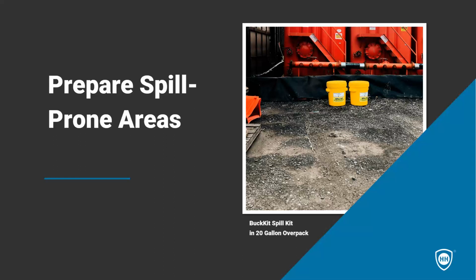So how can we prepare these areas? Now we've identified them, we've looked at some of the preventative measures, but we all know that even with the best prevention, spills can happen. And that's why when you look at your SWPPP or you look at your SPCC plan, there's always an element for spill prevention and for spill response within those plans.